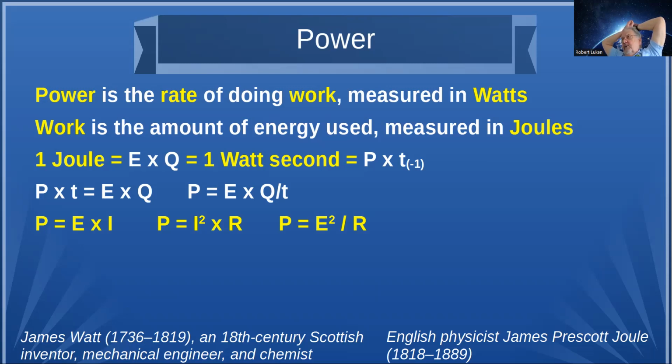But back to your basic question on power, the coax is rated for power. Most of the half-inch coax, like LMR 400 or RG8, I think 213 is the other equivalent, are rated for 1,500 watts or more, which is the maximum power we're allowed to use.